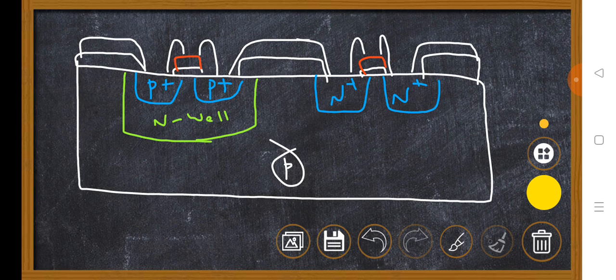Metallization. Which metal are you going to use? Aluminium. Therefore, there is a metal I'm considering. I'm directly going to draw. Remember, that is a very important point. You have to do photolithography and etching after growing an aluminum metal. I hope you are clear.